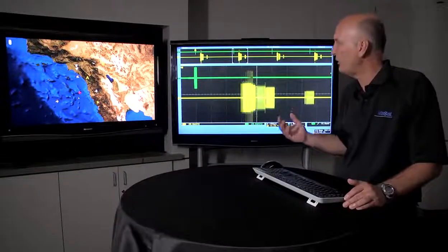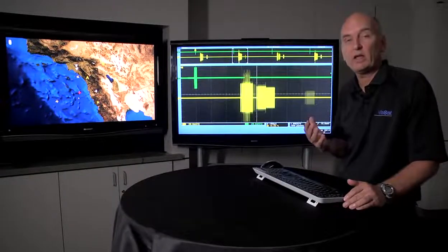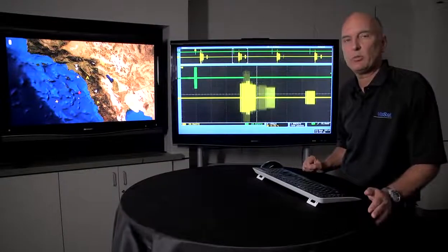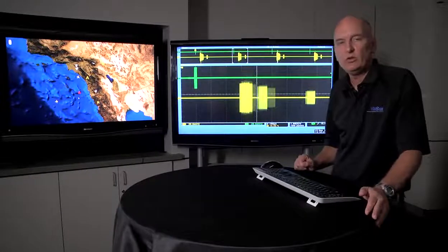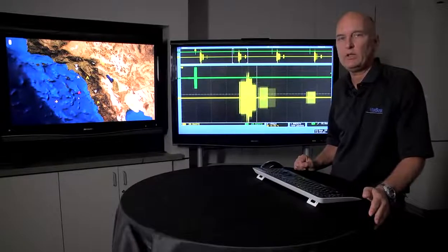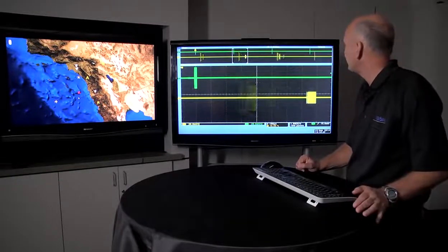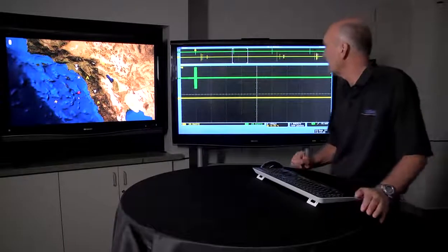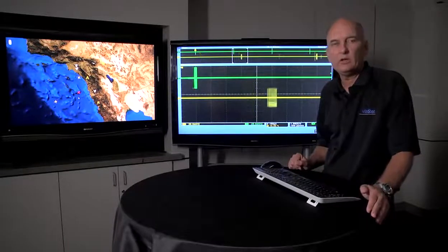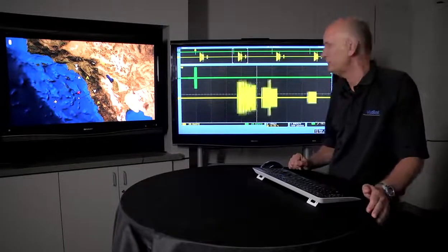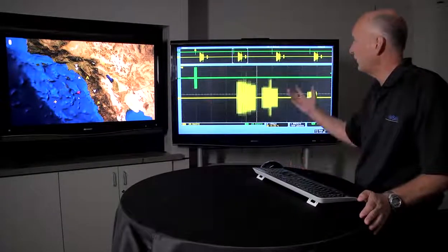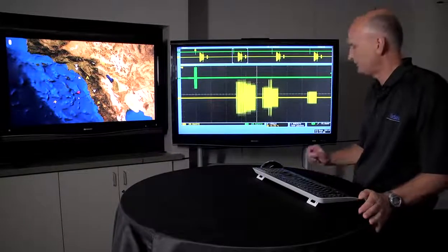This is information that's fed from the interrogation, and we're interpreting that on the fly and having each transponder reply independently. If we switch to a 1/16th reply probability, we should see even less density of signals. And then we'll go ahead and switch back to 100% probability. And now they're all responding and all garbled over the top of each other again.